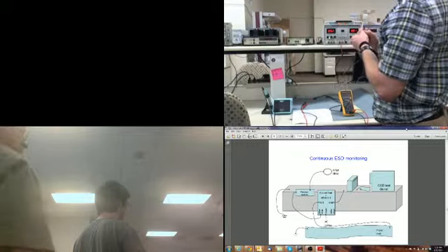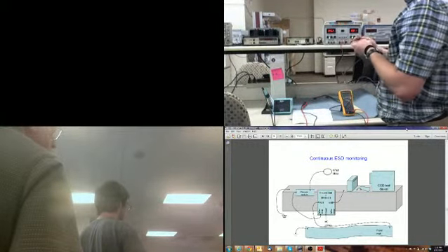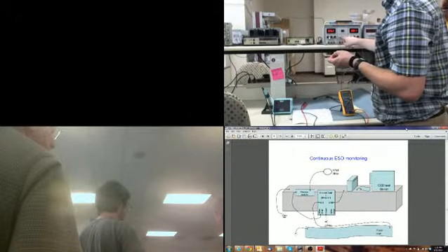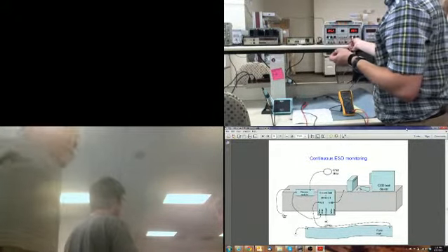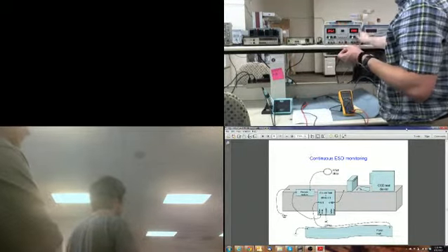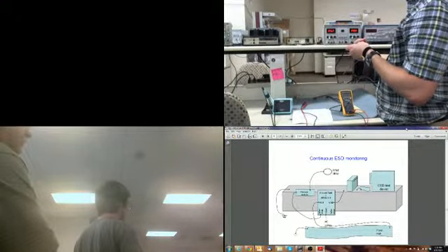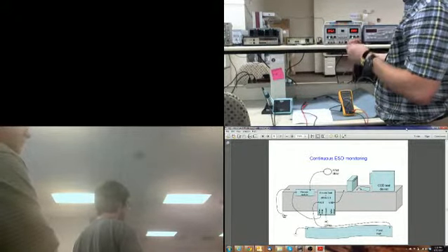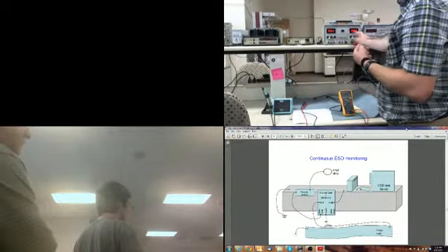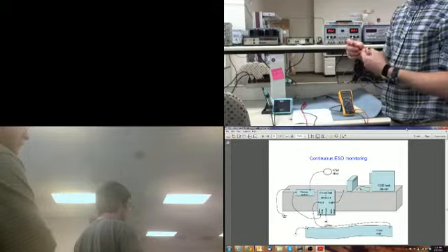It's on 5 volts. So I'll put in there a resistor, a light bulb. Let's put everything in the out position, okay? Now let's put this all the way down, and we'll put the current to a safe level. When you very first start a project, I would say turn the current down, just to be safe, turn the voltage down. And then I turn up the voltage a little bit and the light comes on.